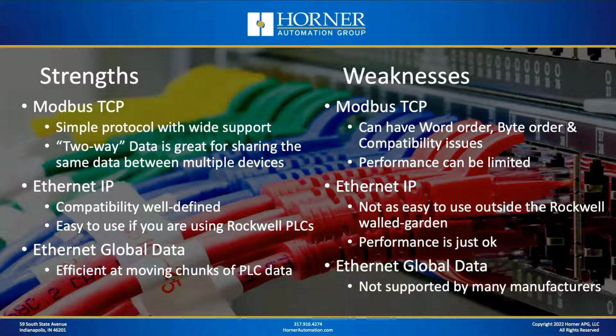Modbus TCP is a simple protocol with wide support. That's its biggest strength. There are a lot of automation companies out there that might manufacture simple devices, and those automation companies are experts at that simple device, that sensor or that actuator, whatever the case may be, but they're not necessarily experts at communication. So Modbus is a simple protocol that's straightforward to implement, and that's why it has been implemented over the years on so many different devices, and that's carried through with Modbus TCP over Ethernet. It's a simple protocol with wide support.